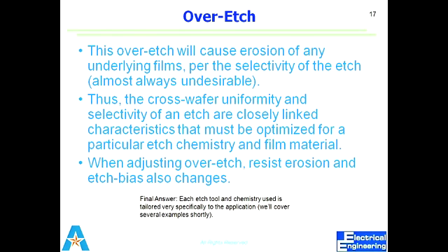If the etch rate is very slow, I can go for 2 minutes maybe. So it depends on the etch rate, because if you have not calibrated that and you have over-etched for more time, it can erode your substrate, or even damage the mask layer you are using, maybe photoresist or any other photo mask. Undesirable etching can occur in that case, because I told you that selectivity is not always infinity to 1. It's always maybe 20 to 1, maybe 50 to 1. So over etching can damage your substrate or the mask films.